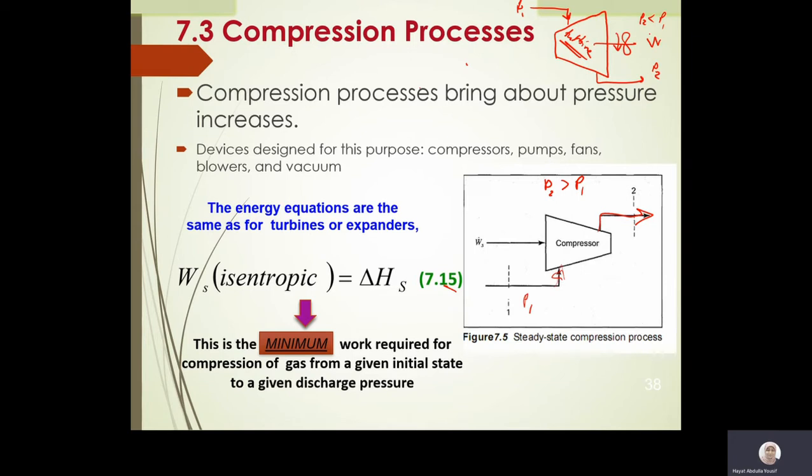And in terms of the taper shape, because of the compression, I get it just opposite. The outlet is smaller compared to the inlet, just to express the compression itself. Keep in mind, the cross-section area is not changing, neither in the turbine nor in the compressor, generally. But that reduction is just to show the compression and expansion process, having it smaller or larger at the inlet or outlet in the drawing. Okay, so that's the sketch or flow diagram of the turbine and compressor.